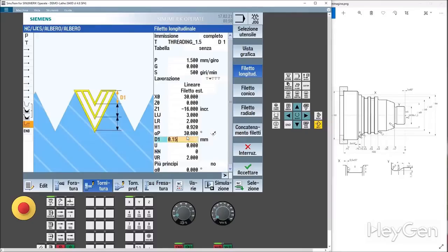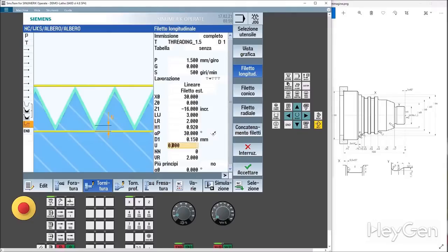All right, what do we have left to do? We have to make the 2 grooves, so we go to groove turning. Here it is. Let's select the tool right away. You see, once you understand the concept, they're all the same. We have a tool for external grooves, thickness 3, and the tip radius is 2.